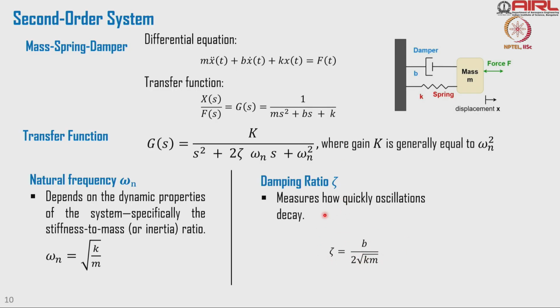So when I write the transfer function in a generic form, I can relate the natural frequency and damping to the physical constants of the system. You can understand what happens if the system is oscillatory, or has a high or low overshoot, by relating it to the physical properties present in the system.